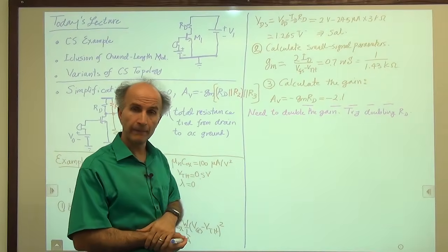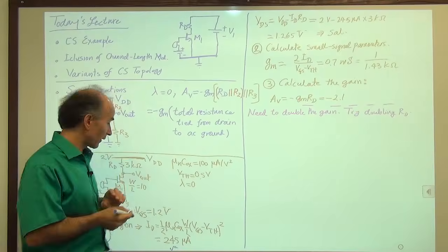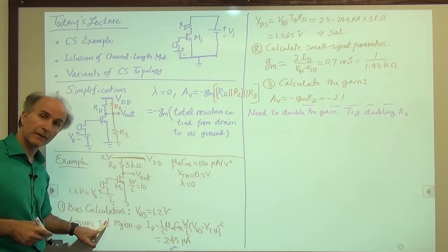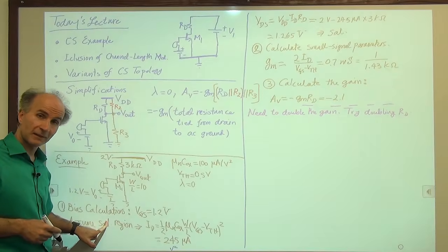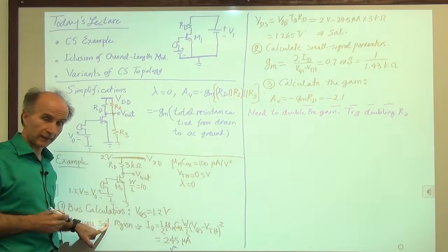Which is fine, but we have to be careful. If I increase this resistor by a factor of 2, I need to go back and check my bias conditions. Is the device still healthy? Meaning, is it in saturation? So let's go ahead and do that.